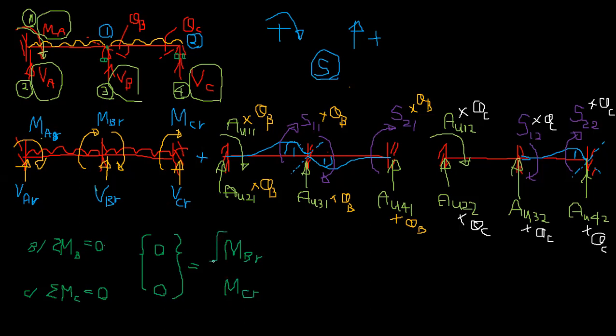So now my B joint is okay. I took this, then I took the bending moment about this, right? Once I add these three structures, I should get this one. If this joint is in equilibrium, the addition of these three structures and addition of the B joint in these structures should be in equilibrium. That is the summary of this method, right?